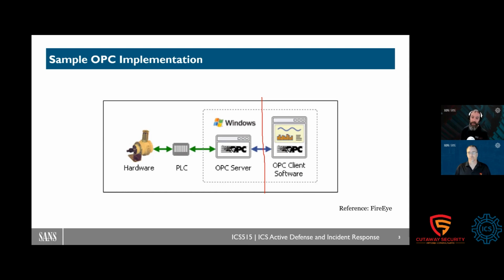It's Open Platform Communications, but we used to refer to it as Please Connect for OPC, because it can be quite a frustrating protocol to get going. So there's a tendency to turn off security controls, allow anonymous communications and things, just so that it will start talking. And of course, once it's talking, you just kind of back away.